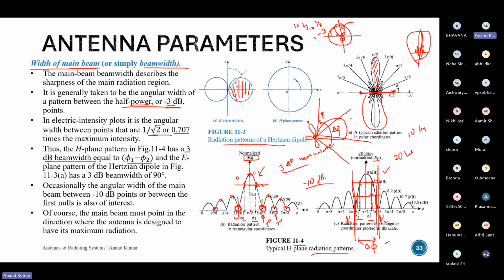When you say your device is within the 3 dB beam width, you are implying that it is receiving at least half of the maximum power your device could send inside the main lobe. That is the 3 dB. And minus 10 is something I'm also not very familiar with, but I've seen it in this text, so I've included it. Minus 10 would mean the device is receiving at least 10% of the power, if I'm doing the math correctly, or maybe 1%, something like that.